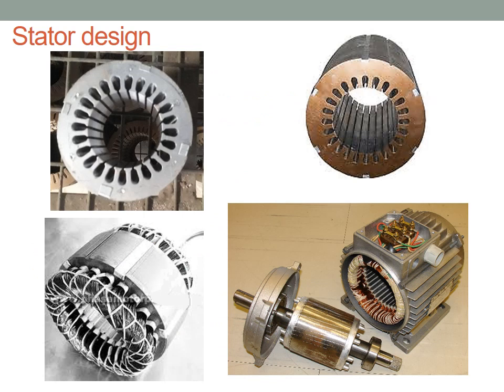So now these are the pictures of the stator core. The stator is made up of thin laminated stampings, with a thickness of around 0.3 to 0.5 mm. These stampings are very thin and varnish coated, and they are stacked together throughout the length of the core. This is the length. To reduce hysteresis losses, they are made of thin laminated stampings.